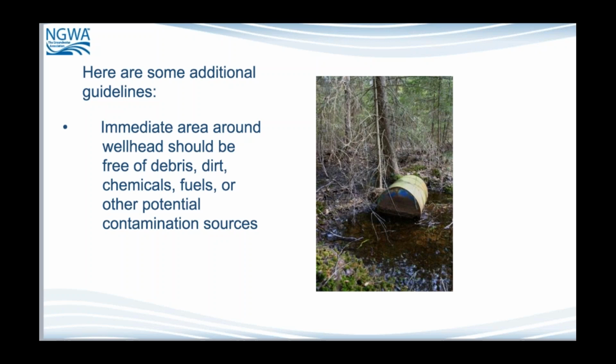Well, the problem is that if you're not using those wells, a lot of times they fall into disrepair. They're not being updated, they're not being maintained, and those can be routes all the way down into the same aquifer that you're going to be drilling your new well into. So you want to make sure that you find those on your property. You get them sealed up properly, because you don't want to leave them there to be a route into the water you're going to be drinking.